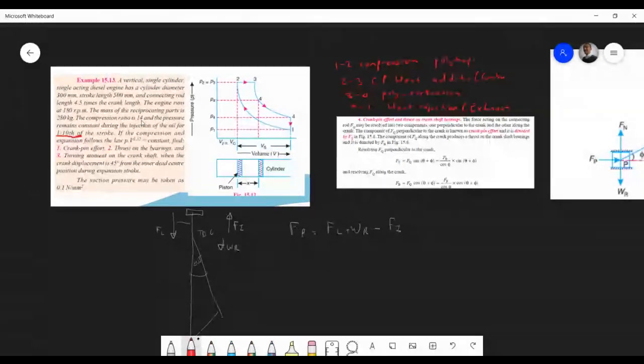So I'm not going to make it 1/10 of the stroke. What I'm going to do is work out the pressure from... Oh, but it does make sense. The reason they say it's 1/10 of the stroke is that the pressure will be essentially the same in the cylinder, so they chose an arbitrary point where you can have some kind of pressure difference. That's all it really is.